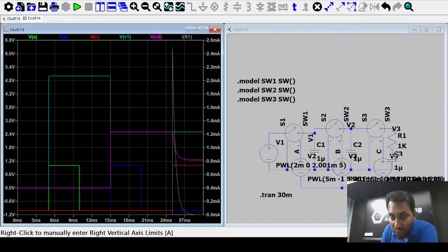And once capacitor C3 is charging, the current is V2 minus the capacitor voltage upon resistance. Initially it was 0, so V2 minus 0 upon R. As the capacitor charges, the current is V2 minus V4 upon R, and V4 is increasing, so the current is decreasing exponentially.